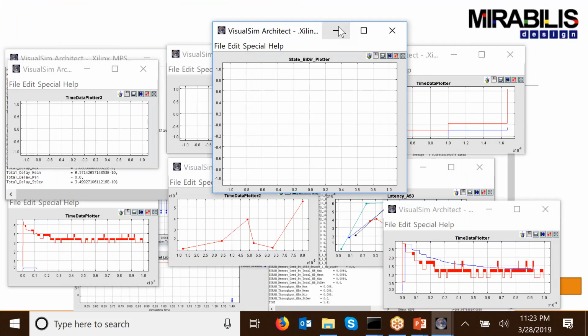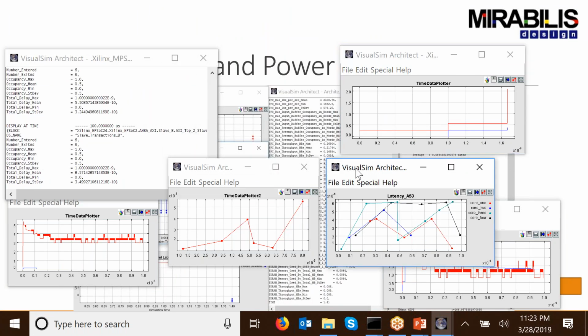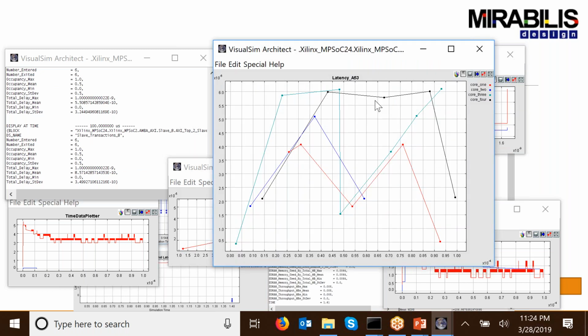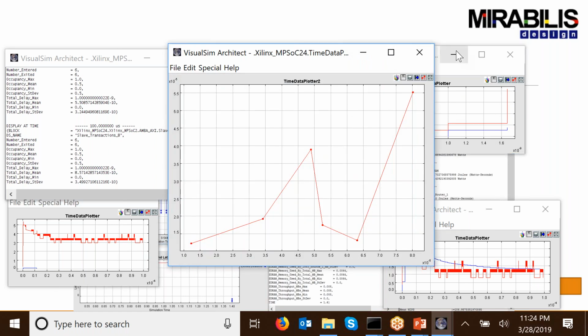Now, when I start looking at some of these statistics, I'm not using the second processor, so you don't see some of these things. But to give you an idea here, I get to see what was the response time on each of the cores for the different tasks that are executing. Similarly, I can see the total response time for the entire task itself, which is the task graph. So this is a sequence of things. If you notice, many of these points are right here, but you're starting to see a lot of spikes. This one finished at 440 microseconds, while this took about 55 microseconds. So that's a fairly large range, and you want to understand why you have such a huge range.